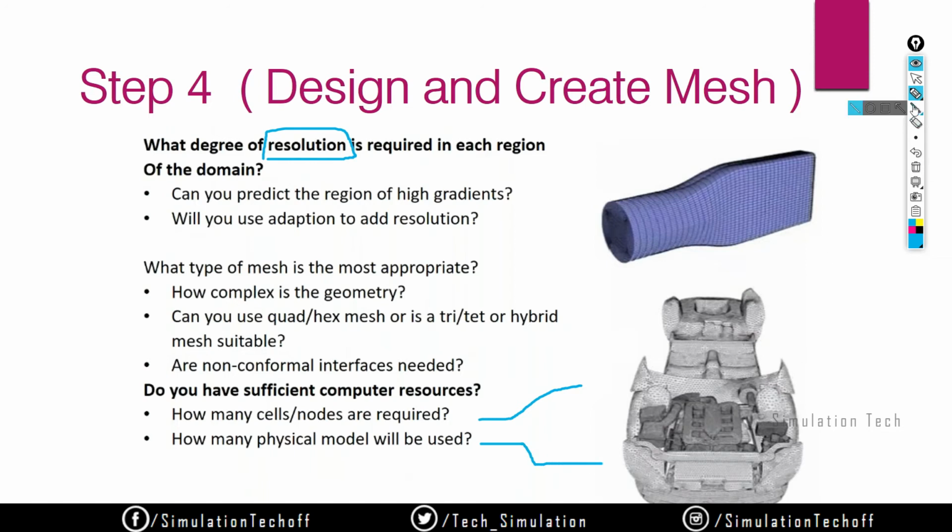So I know that when a liquid flows from here, it has maximum turbulence nearby this region because the volume is contracted nearby the edge. So obviously you have more turbulence nearby this edge of the liquid. So you need to create a proper mesh nearby this region, otherwise you can't observe what has exactly happened in this region.